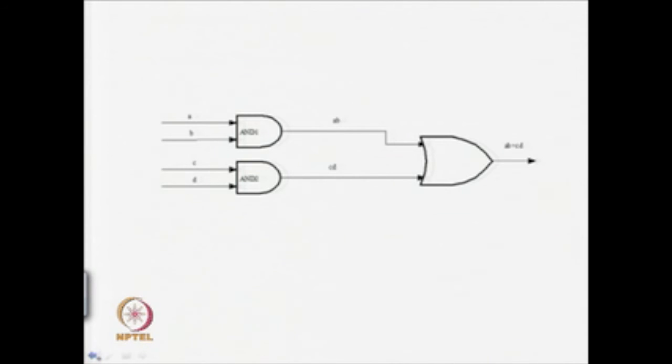So, basically, if I have any Boolean logic circuit, just for explanation, say I have 2 AND gates and 1 OR gate, and the input variables are A, B, C, D. So, with these 4 input variables, and this circuit given to me, I can write the function for this particular circuit. This is nothing but a sum of products, that means A into B plus C into D.